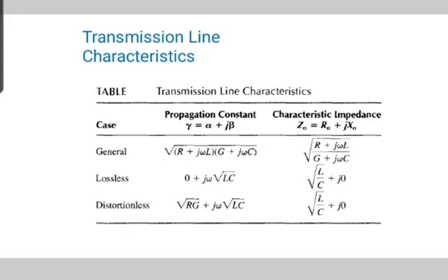When a complex signal containing many frequencies, such as voice, is applied at the sending end, then at the receiving end the different frequencies are attenuated by a different amount. So the received waveform is not the same as that of the sending waveform, and it is known as frequency distortion.